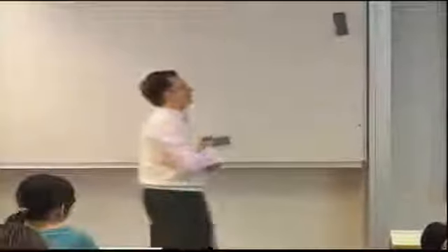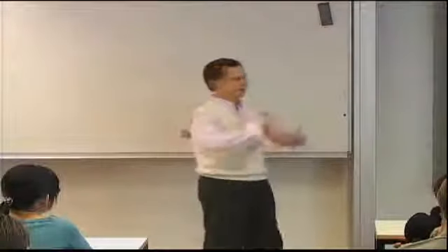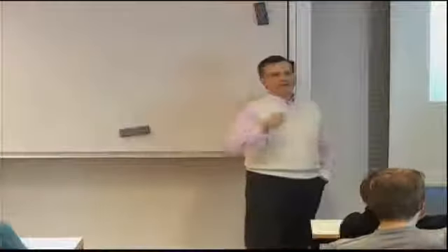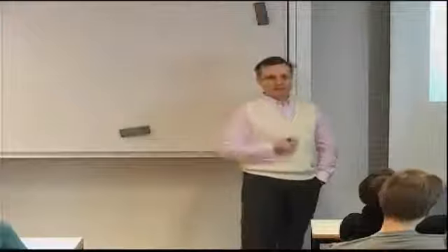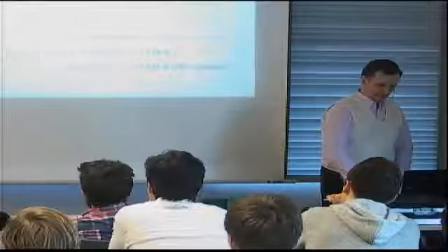So it will be interesting to see how much of this 25% transfers over, or even does the trend change. But at this point, laminate A is significantly better if you want a high buckling load. Any questions so far? Okay.